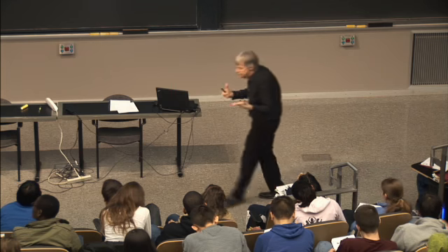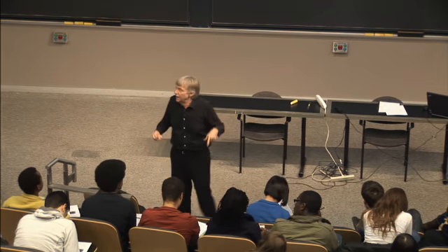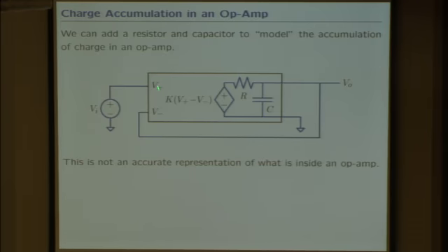The op-amp senses the voltage at the input and the output and does something to change the voltage at the output. If the positive voltage is greater than the negative voltage, it pumps charge into the output node. If the opposite occurs, it sucks charge out.